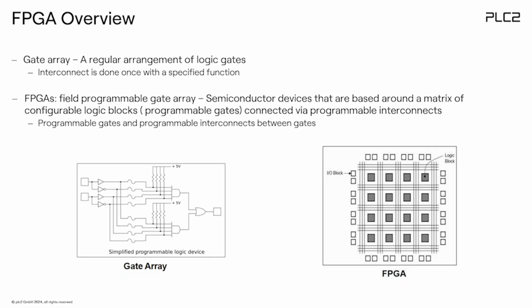For somebody who doesn't know what an FPGA is, I'll give some very basic information. This would be a gate array, which means prefabricated gates, like Boolean gates, and then it could be a PAL or a gate array. If this is a PAL, the former technology, then we have some fuses. During programming we basically burn the fuses away, and then we get the resulting structure. But this is very old, and we're not using it anymore.